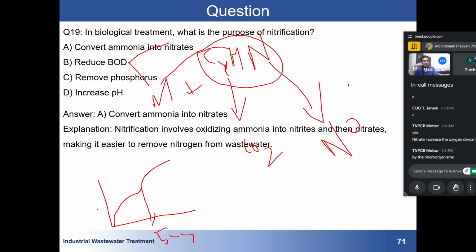Not BOD, what is this line? I don't recall. But generally, within 5 days all the carbon gets converted into CO2 and so on by microorganisms. Oh, sorry, you have written something else. But I'm saying, within 5 days all the carbon is getting converted, and after 5 to 7 days all the nitrogen will start getting converted.